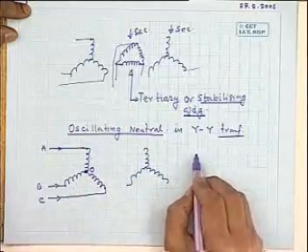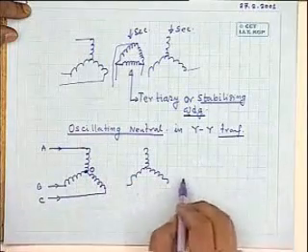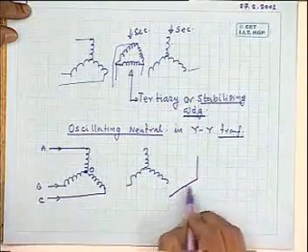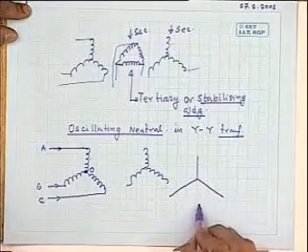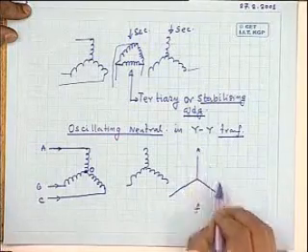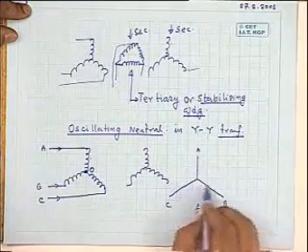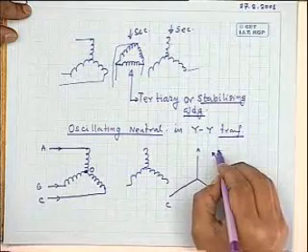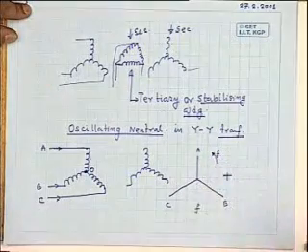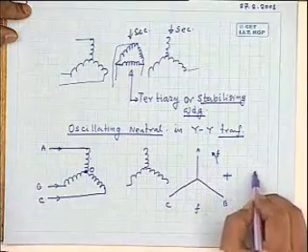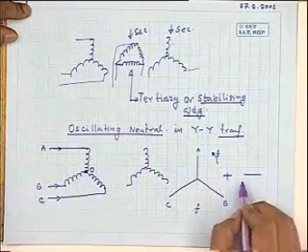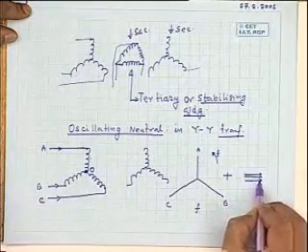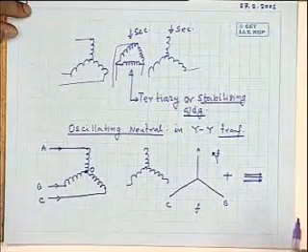Now, therefore, in any phase voltage, that is, in each winding, if I draw the phasor diagram, suppose this is the A phase voltage because of the fundamental frequency. This is A, this is B, this is C. This phasor rotates at a frequency of f or omega. Plus another third harmonic voltage will be there in each of the windings, and these voltages will be in phase and of equal magnitudes.